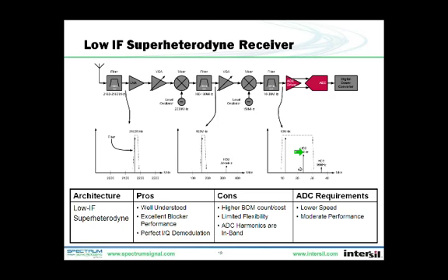Now, on the bright side, for the ADC, this architecture allows for a fairly low sample rate and a limited bandwidth. It also reduces the importance of clock jitter, reducing the complexity of the clocking implementation required to drive the ADC.